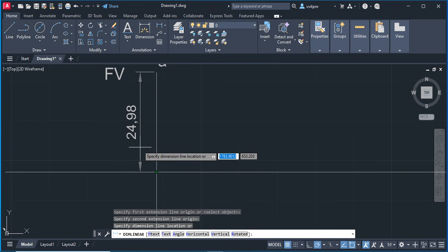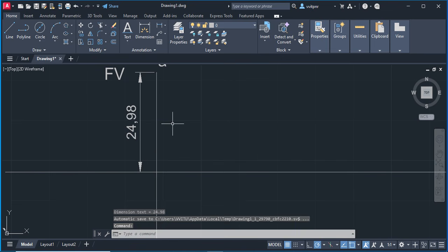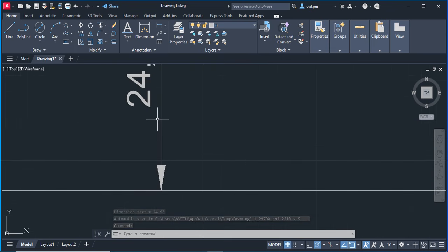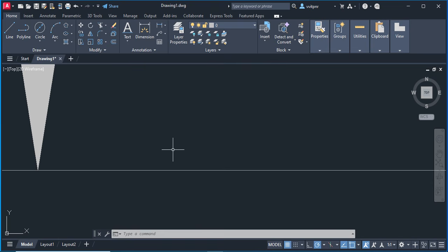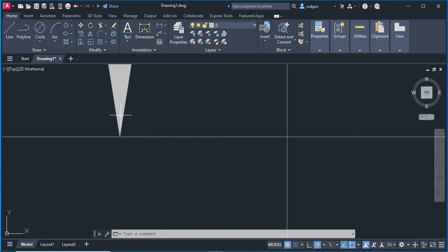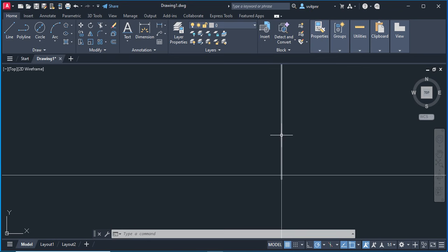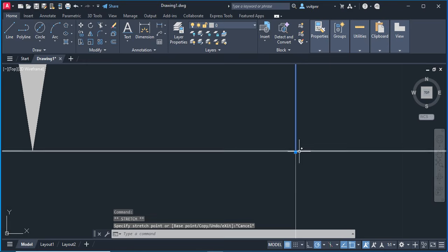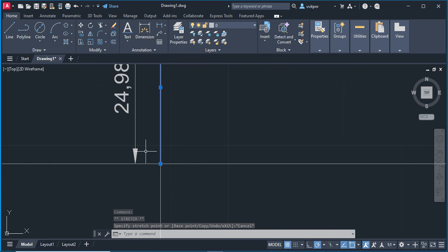So you can see here, but actually this line we were given as 25 length. So you can see that initially we did not draw it correctly. Select this and move it to this point. Why was the dimension shown here as 24.9598 instead of 25?